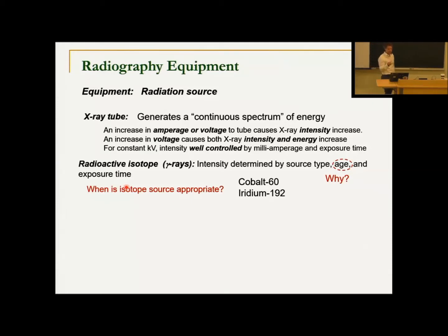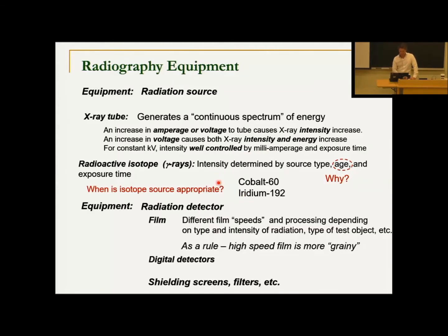Well, X-ray tubes need current. They need power, electrical power to operate. These are natural. So if you are going to the field and you don't have ready access to electricity, these kinds of sources are preferable. Also, these tend to have higher energies and higher penetrating ability.